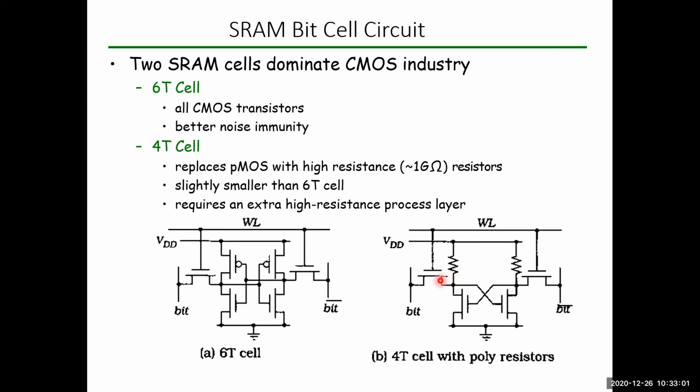So that's why this particular 4T cell is called a high power dissipation circuit, whereas this one is a low power dissipation circuit. Another disadvantage of a 4T cell is that it requires more space to draw the layout, and it also acquires more space to construct any kind of IC for this SRAM cell. So these are the differences between the 6T SRAM cell and the 4T SRAM cell.